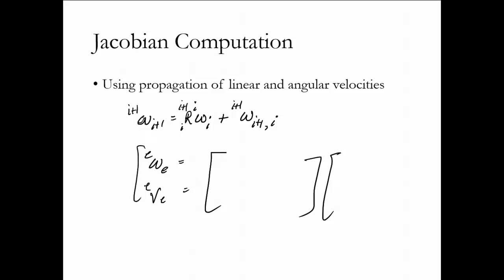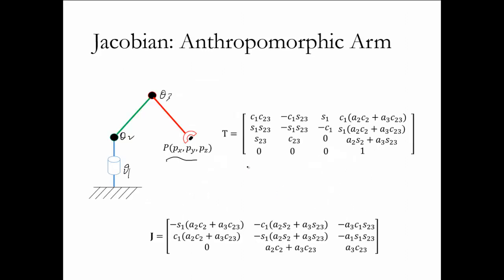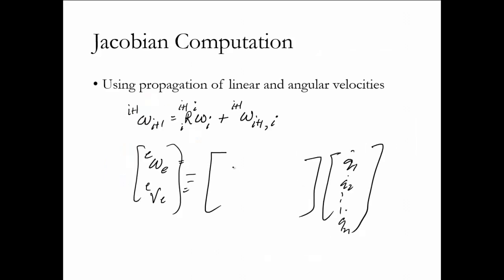So accordingly, we can use those and open them up, and then put it this way to get the Jacobian. Here we have the simpler columns: e1, e1 cross a1E, e2, e2 cross a2E, and similarly up to en and en cross anE.